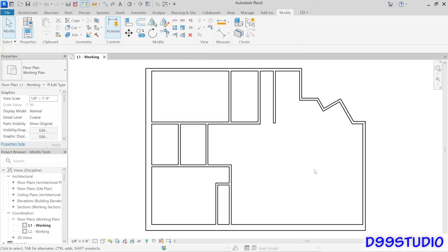Okay, so that's one of the options that's on the options bar. And the thing to be aware of with the options for these commands is they remain persistent. So the reason multiple was already turned on for me is because the last time I used the Copy command, I checked the multiple option and Revit remembers that. The same is going to be true for the other commands.